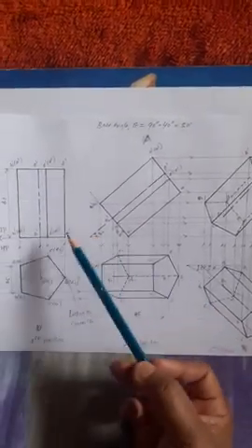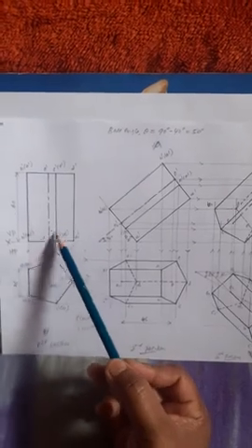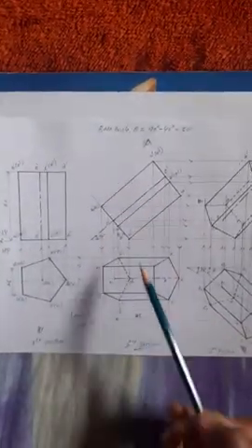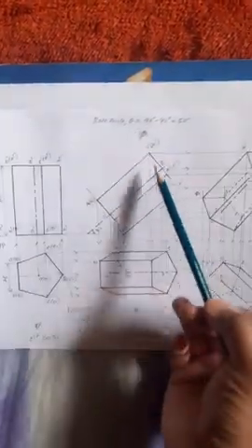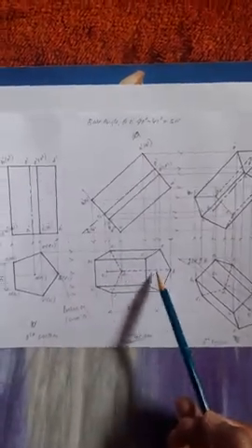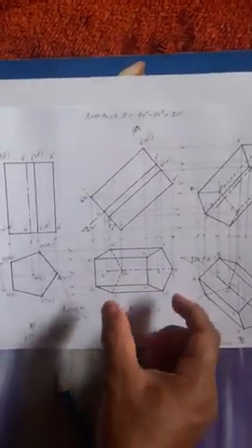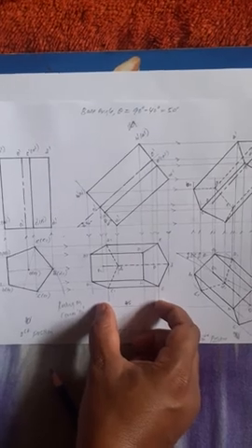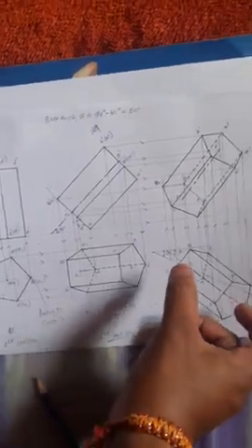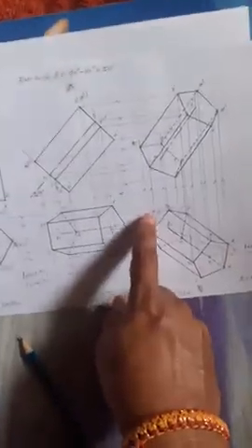Now see that the axis in the first position, axis in the front view, is 60 mm. In the second position, front view, also it is 60 mm. When viewed from here, the axis O1 O has now become a reduced length, that is 45 mm. Now this 45 mm I want to place where VP at 30 degree, means whatever the dimension given in VP, that I want to show in HP. Now draw the 30 degree line.